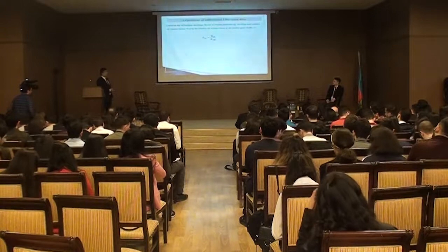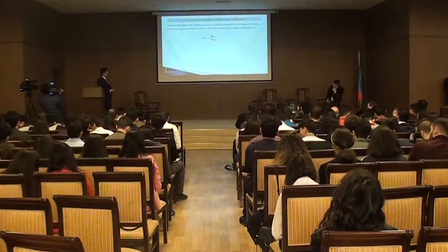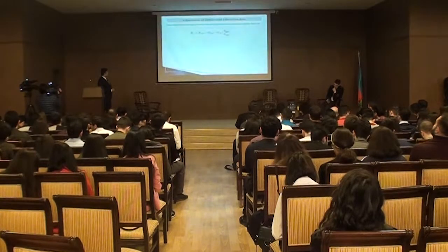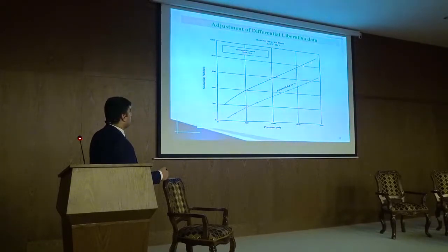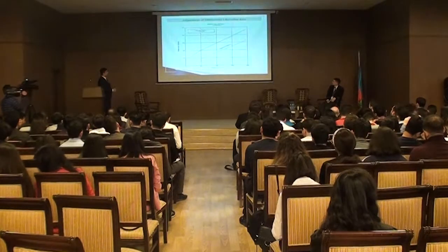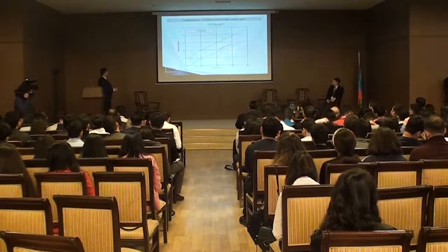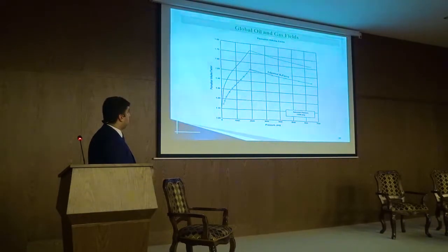By using these software packages, the software will do this adaptation for us. For example, it is a simple illustration. We get solution gas-oil ratio from the DLE test. And by using separator adjustment of gas-oil ratio, we got that the gas-oil ratio should be lesser. And it is the same for oil formation volume factor.